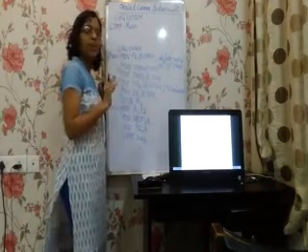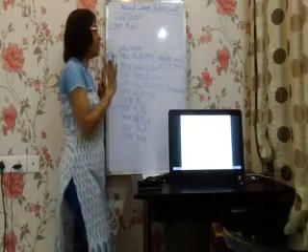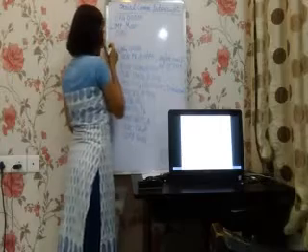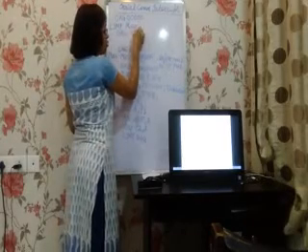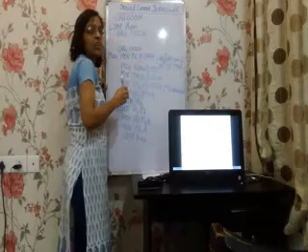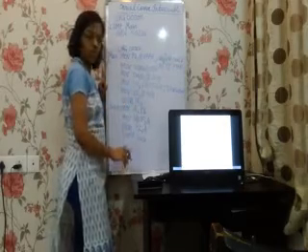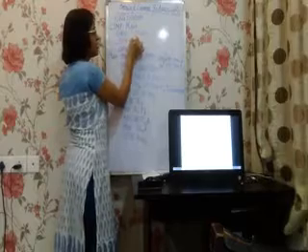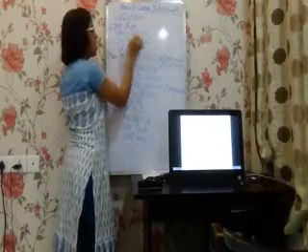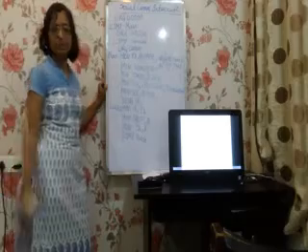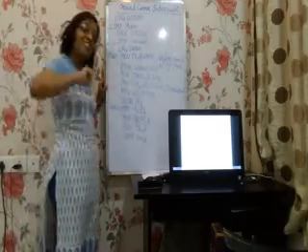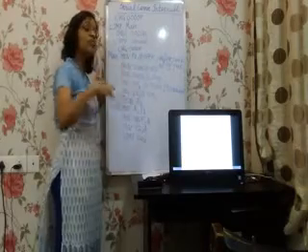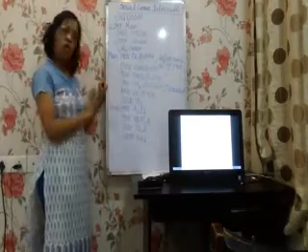That much is not sufficient for me. So what I do in this subprogram, I give ORG starts from 0023H, right? Okay, ORG 0023H, and I give a LJMP serial over here. So I write down my serial communication program not from this space but into some other ROM space. Hope you have understood up till here.